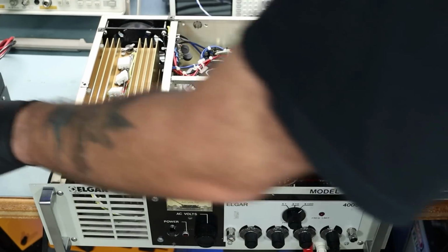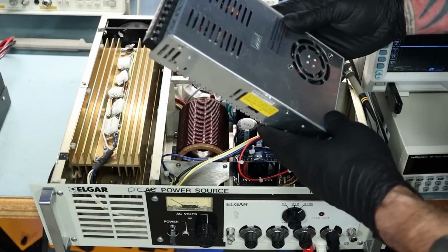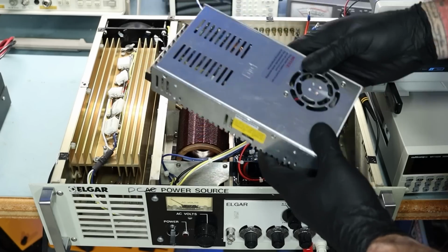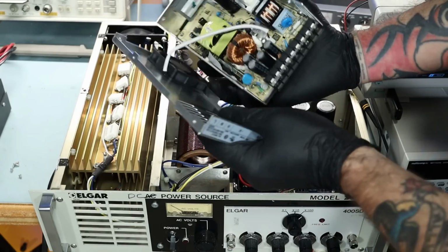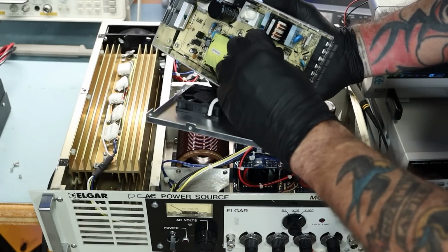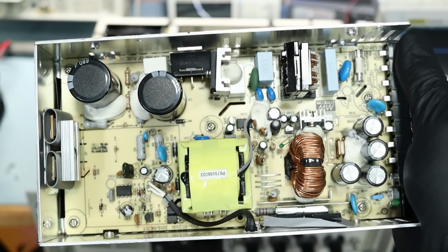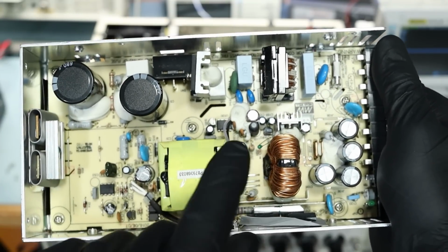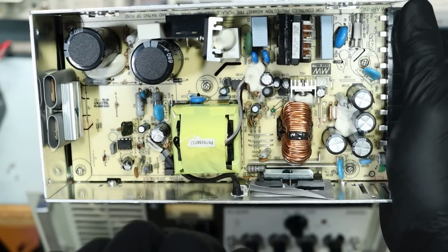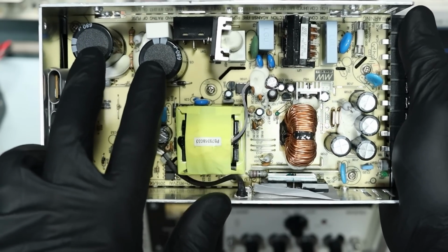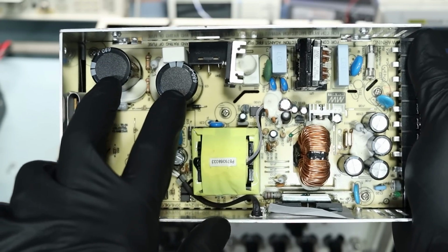Let me just show you in comparison, this is a switch mode supply that is also 350 watts. So let's pop the cover off that just so I can show you the capacitors in this thing. I don't recommend taking things apart on top of other gear, but we're trying to keep in frame here. So I'll pull this fan. The reason these switch mode power supplies are so awesome compared to old school linear supplies like that one is that this is switching at a much higher frequency. So these transistors are switching on and off, goes through this transformer, gets rectified, and these capacitors, because there's such a fast rising pulse, these capacitors don't have to provide much energy.